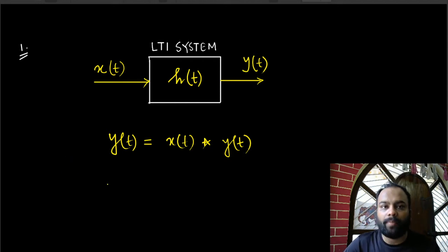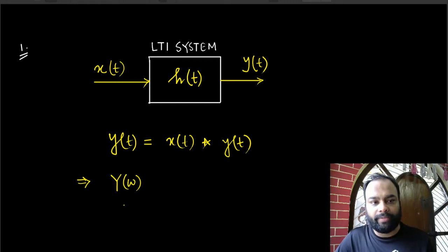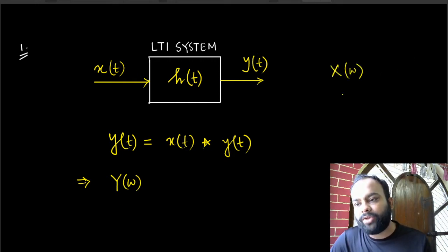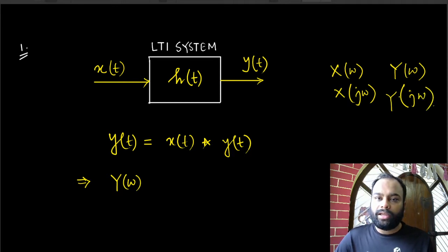Absolutely not. And from the convolution theorem of Fourier transform, if the Fourier transform of y(t) is Y(omega), and just one more thing, one of you asked me through an email that if you follow Oppenheim's book, it does not write X(omega), it writes something like X(j omega). You shouldn't be confused about this. The idea is that this is just a different notation. Instead of X(omega) or Y(omega), if you write X(j omega) or Y(j omega), there would be no change in any of the derivations whatsoever.